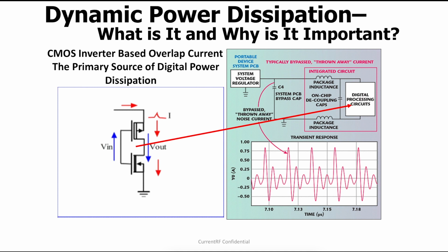Dynamic power is the power draw from system power supplies, generated by the current created by logic and switching circuits changing states. This type of power dissipation is the primary source of power draw seen in microprocessors, memory, transmitters, etc. Dynamic power is usually included in, and not broken out, in the total power consumption listed in device data sheets.